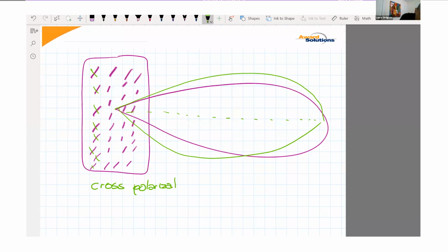So those are 4 layers, 4 antennas, 4 transmitting antennas. And in this case, your kid has 2 receiving antennas. So in that case, it will be 4x2. You can use 4T4R if you transmit the same information in the 4 transmit antennas, right? In that case, it wouldn't be MIMO because it's the same layer in the 4 antennas. You're using just transmit diversity.